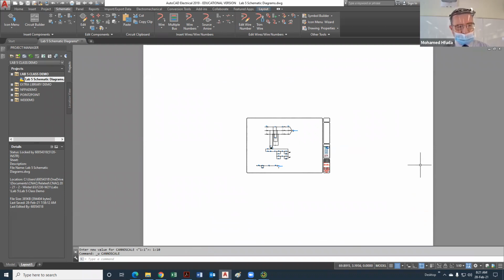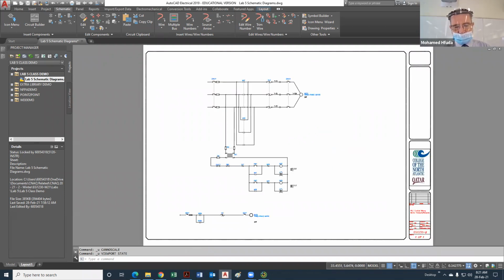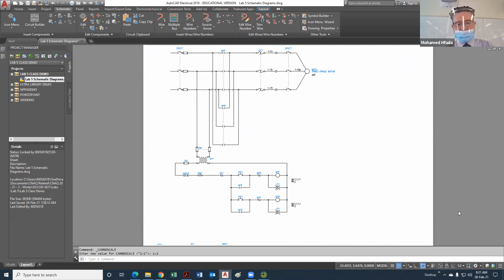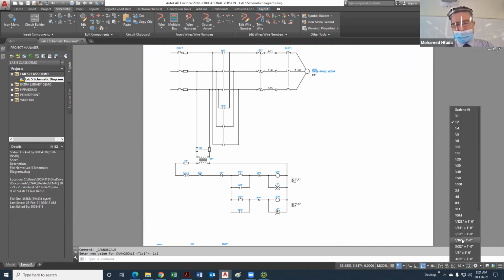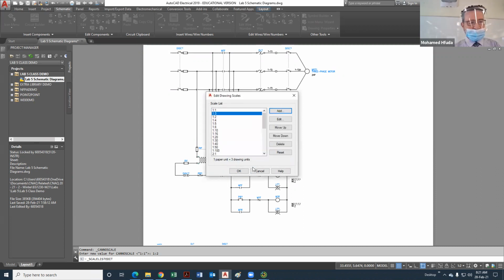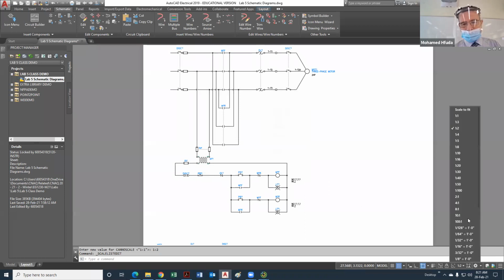You see, this is where it gets interesting. 1 over 0.3 is 10/3, so it's 3 point something, 1 to 3. 1 to 2 is not going to do it. So it's 1 to 3. You can create a custom scale, as we did before, and call it 1 to 3. Just because you called it 1 to 3, it doesn't mean it's 1 to 3. You have to set the scale here. That's just the name. It can be even your name. It doesn't matter as long as you know what it stands for. 1 to 3. I'll say okay. Okay. And let's choose it.